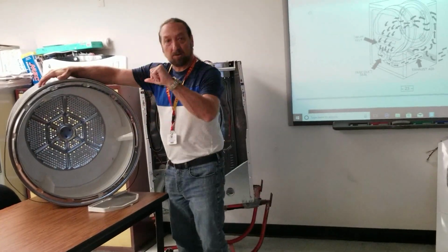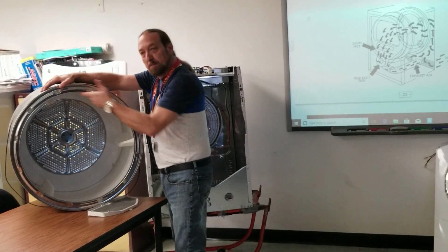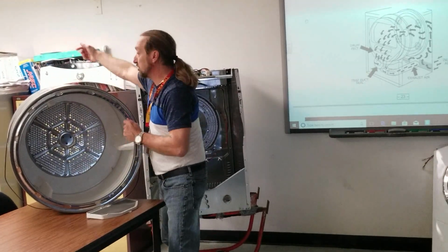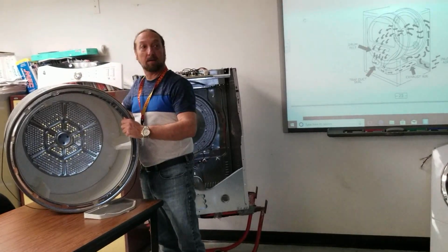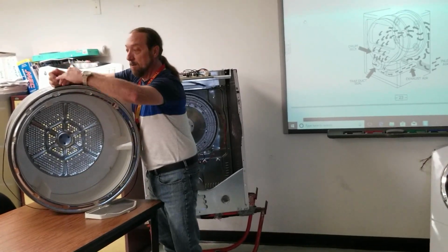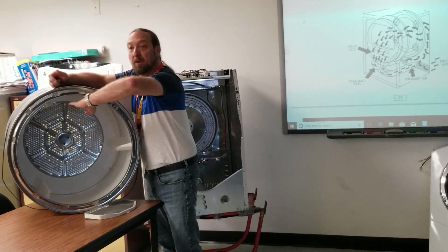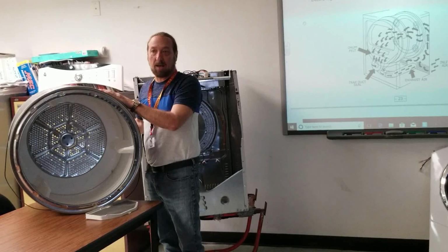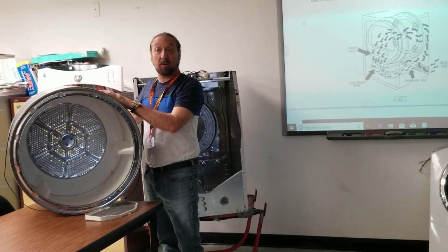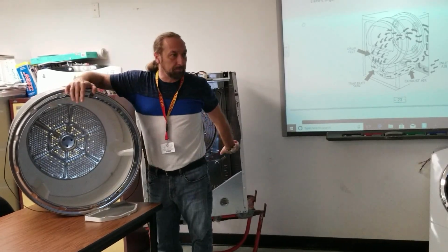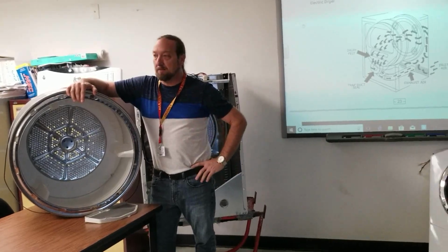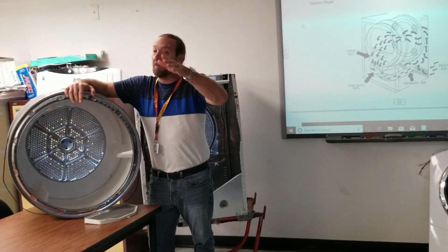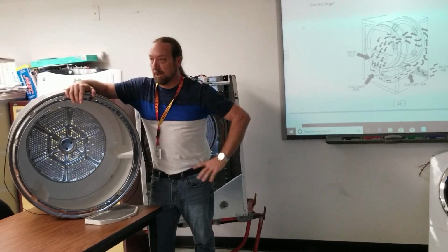So here's the problem. If you have a bad drum seal and we got this negative airflow, we're supposed to pull air over the heater in the back and come in, but now I'm pulling in air from here. So what's happening to my air back here? Either it's stopped or it's not enough air and I overheat my element. If I overheat, the elements sag. We talked about this just a minute ago. The elements don't get enough airflow, they start to sag, and then they break.